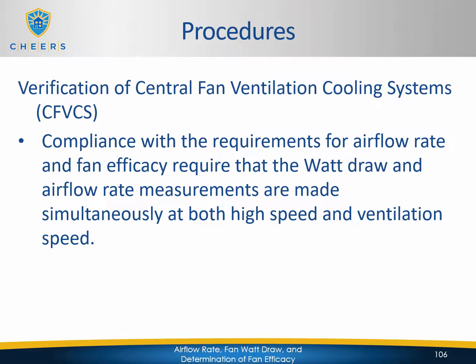Now let's take a look at central fan ventilation cooling systems. So what is that? This is where you will have the HVAC system act similar to what we call a whole house fan. We talked about this a little bit in the Title 24 section. With a whole house fan, you open all the windows to the outdoors, and you turn this fan on when it's cool outside. This fan will draw cool air in through the windows into the home, and then exhaust that air into the attic and then out through the attic vents.